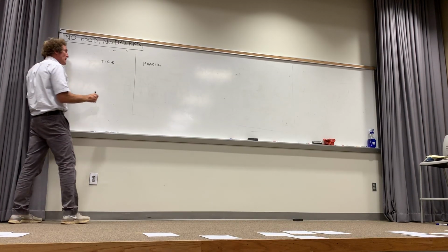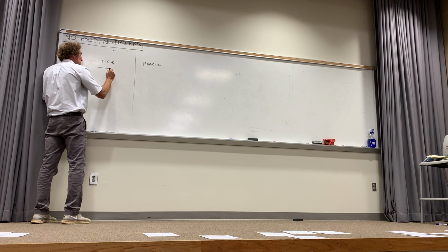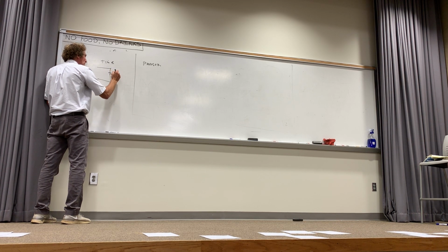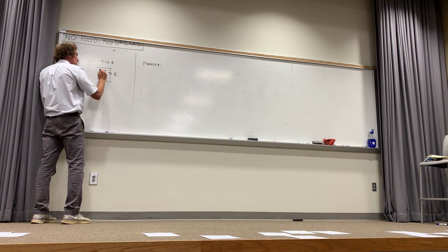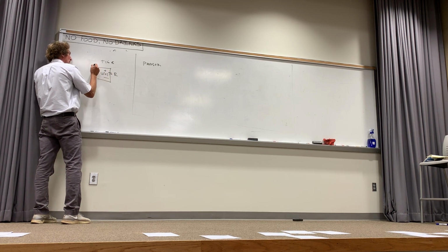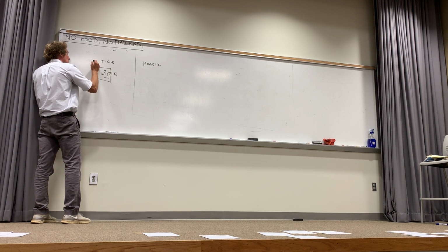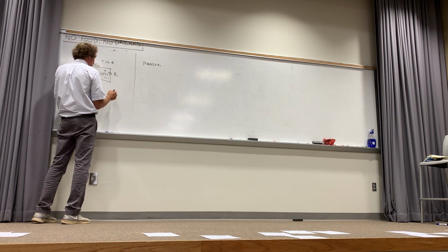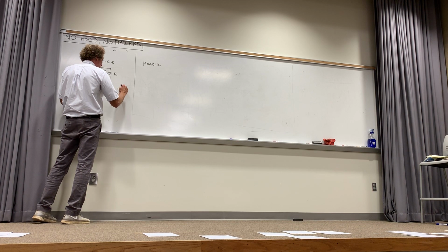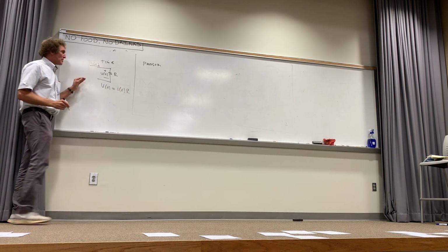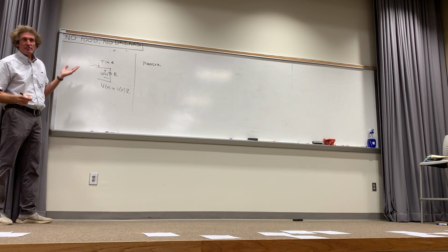Now, over here, when we have a resistor, R, and it has a voltage across it, plus to minus V of t, and a current going into the positive terminal, the relationships are V of t is equal to I of t times R. This shows you how the voltage is going to be measured.